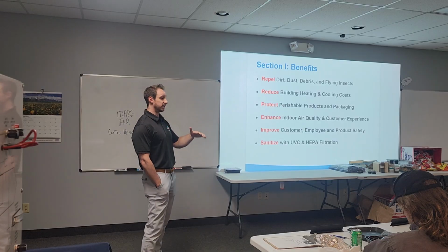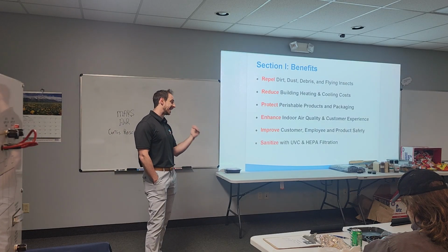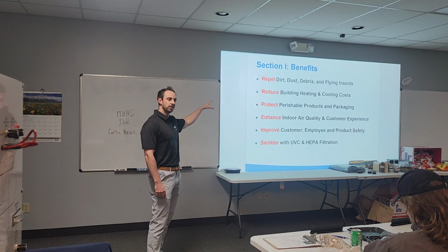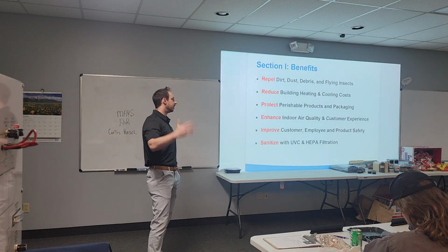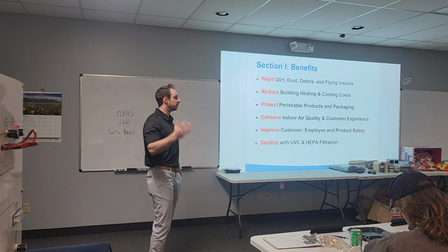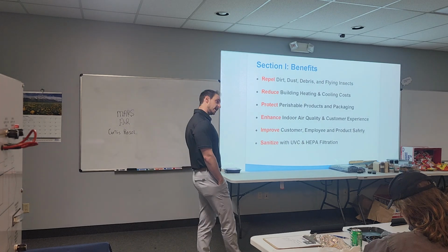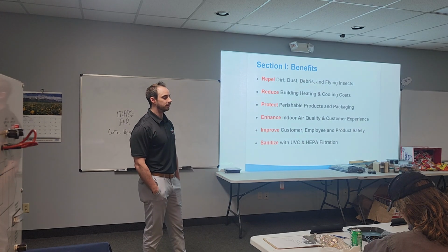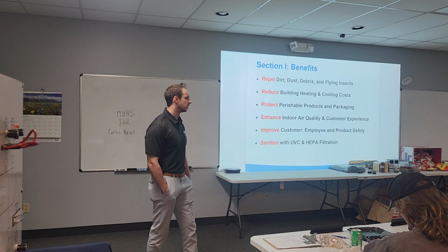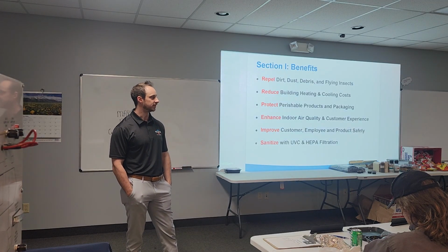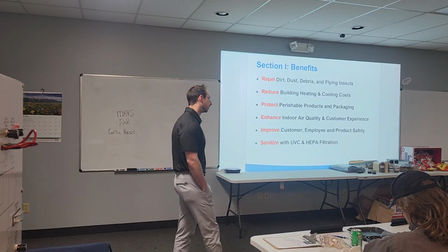Running the air curtain is really going to maintain those building temperatures. We're just running a low power output air curtain, but we're preventing a potentially 150 ton compressor from cycling. ECM motors? We use PSC motors. ECM is moving that way, so I'm sure that'll be more apparent in the coming months and years, but right now we use PSC motors.